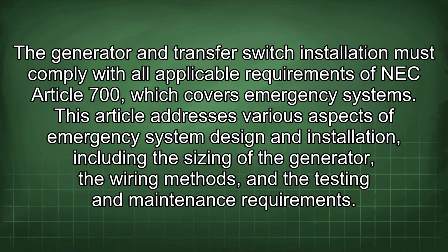The generator and transfer switch installation must comply with all applicable requirements of NEC Article 700, which covers emergency systems. This article addresses various aspects of emergency system design and installation, including the sizing of the generator, the wiring methods, and the testing and maintenance requirements.